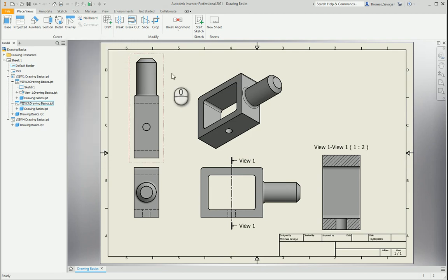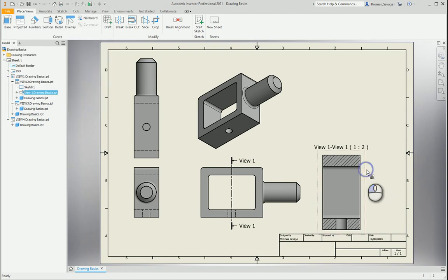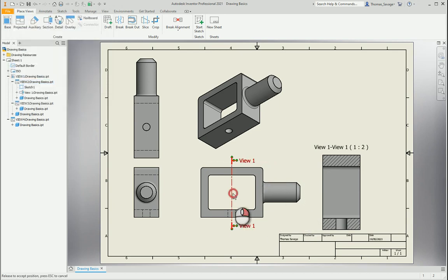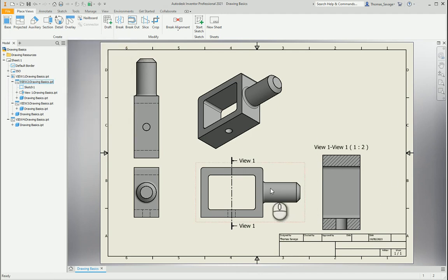Because if we just double click on the section view we've created, it doesn't bring the options up if you wanted to do full or distance on the section, whereas if I show you here, it now gives us that option of the depth, whereas on the other one it doesn't, in case you wanted to change it. Yeah, very useful. I use that quite often.